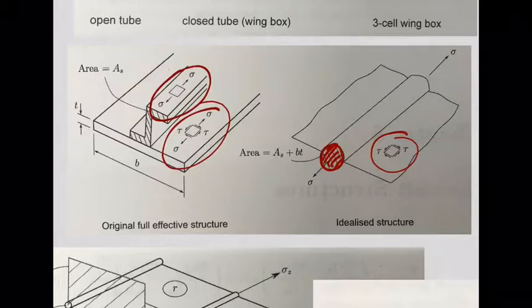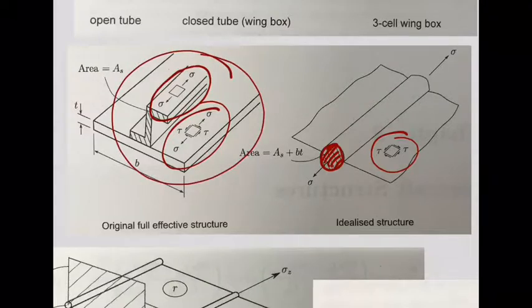So this is very different from the real structure, where the direct stresses and the shear stresses are all combined. Another simplification is on the geometry. In this idealized cross-section, you have only a skin which we assume to have zero thickness, and a boom with a circular cross-section, so you only need to know the area of this boom.